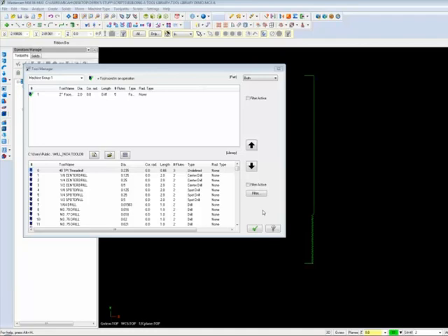I know I've seen a little bit of it, but it's not going to take care of everything because there's so much more offered. Basically, the idea will be that your basic tool definition will come in, but then you're still going to need to go into the new tool manager system and actually add your holders, and add a lot more data about the actual material you're cutting, tensile strength, all that kind of stuff.